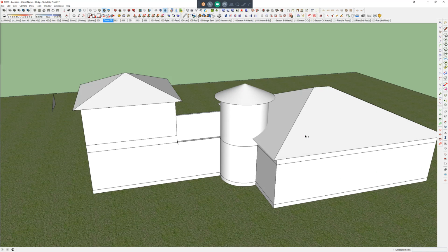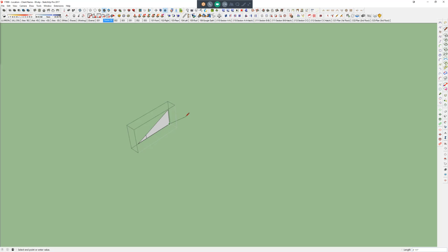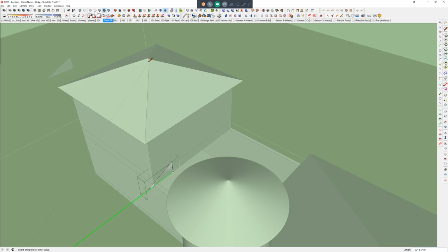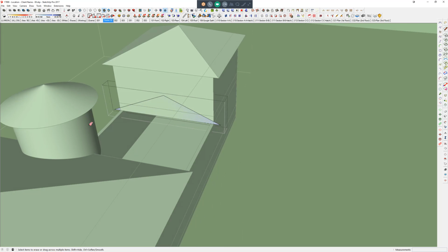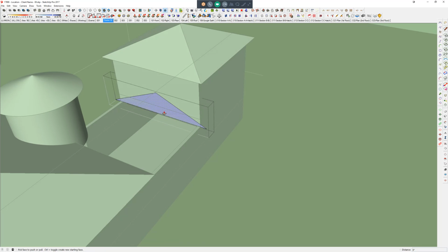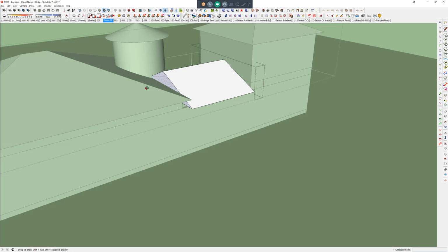So if you have these perfectly rectangular roofs, it's always easy just to draw the center point where you actually want it to be. So even this one, I'll find this center point, come up using my references, and this one's going to be a little different since I know there's no hips per se. I'm just going to rotate that around, and now I have my perfect triangle that is both sides. Does everybody see what I did there? Pretty simple. And then I can run this.